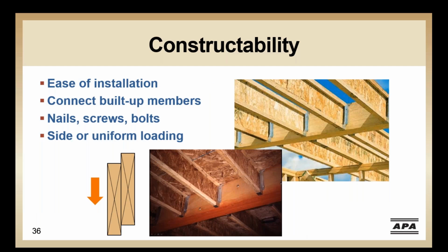The choice of a build-up beam versus a single beam will depend on the contractor, but each has its advantages. Build-up beams can be easier to handle and fasten in place. This is especially advantageous in renovation work, where beams may be hard to get into place due to existing additions. The downside is needing to design and install these connections to transfer the load to all of these members.